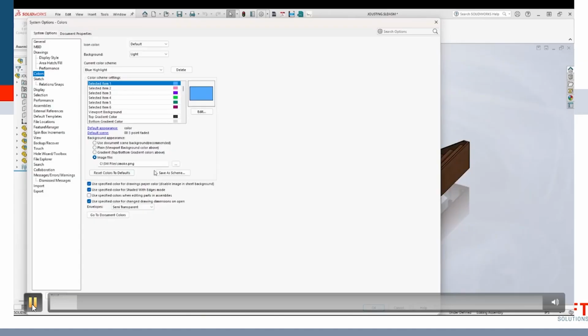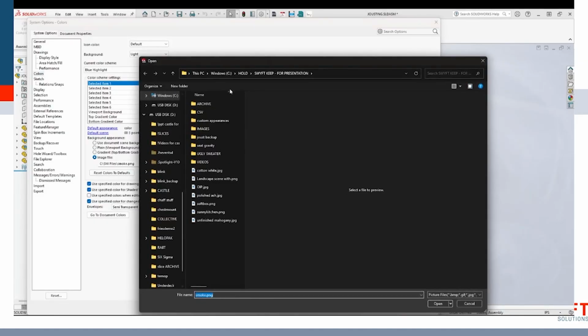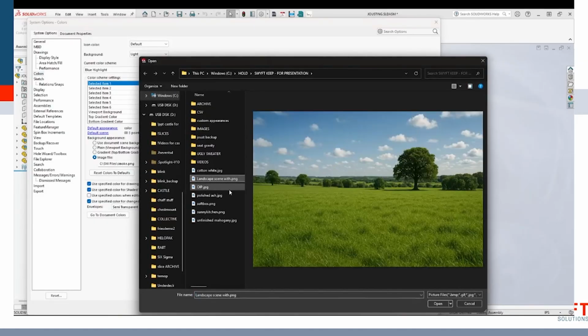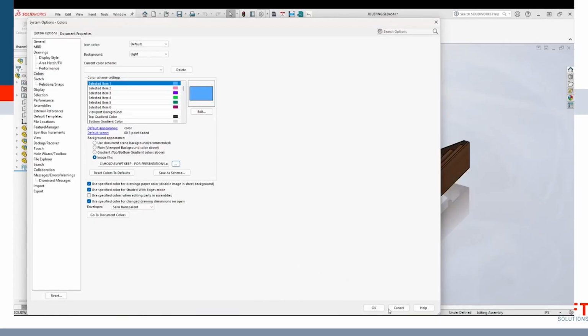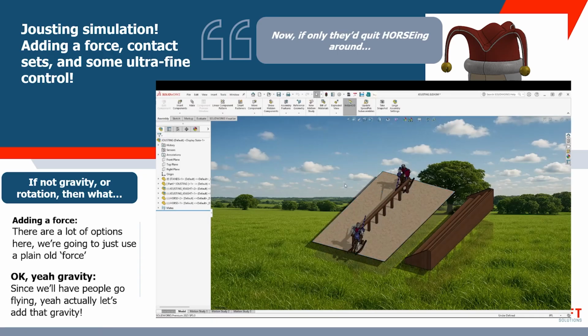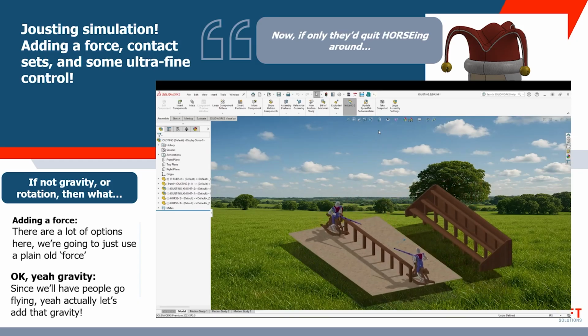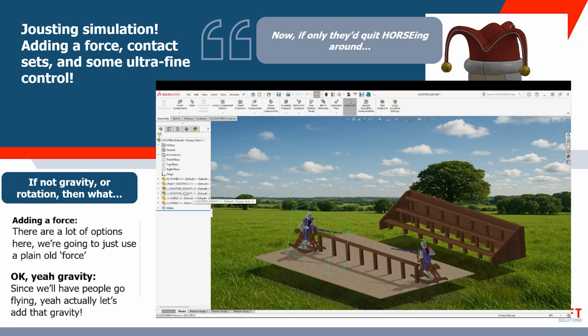Okay, I did want to show that SolidWorks can render the environment that you have set. There you go. So right here in your motion analysis. If you wanted to give it a different background, I just have that landscape that I generated for our background. I changed my settings to be realistic view, added shadows, turned off the hard edges. That looks pretty good. Let's do some motion analysis. Got to switch my configuration for the Black Knight, of course, so we can tell them apart.